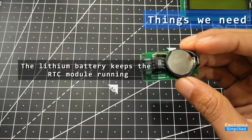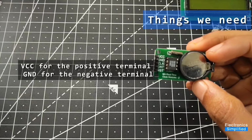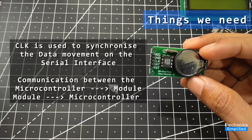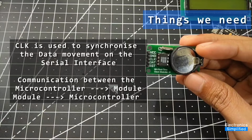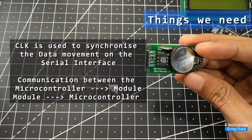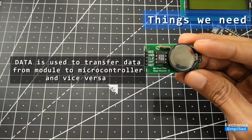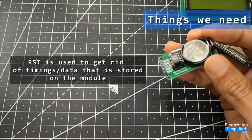This module has different pins. As you can see, it has a VCC, ground, clock, data and reset. So basically VCC and ground is something that most of the modules have. Clock is used so that it can match the clock timings of the data frames, and the data is basically to receive the compiled timings given from wherever the program is being uploaded. It could be a computer, it could be a bootloader. And reset is to get rid of the timings that are actually stored on it.